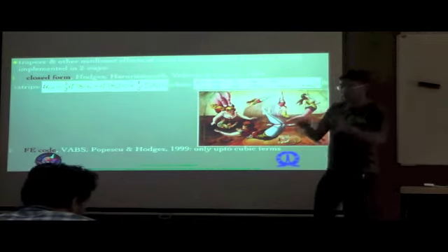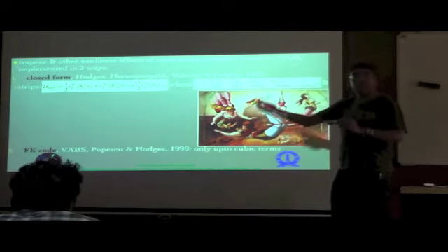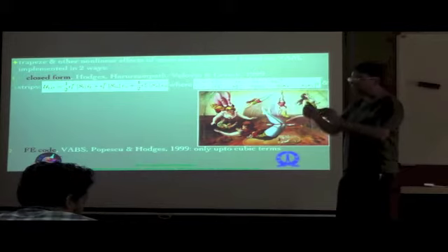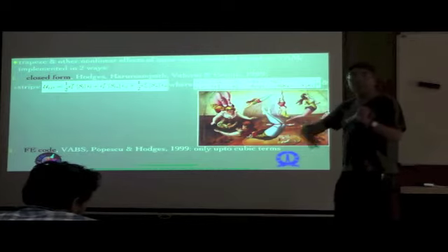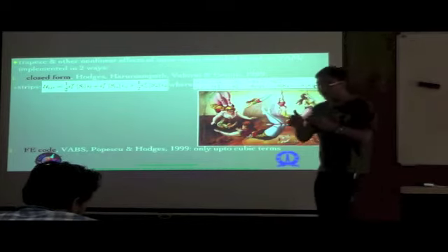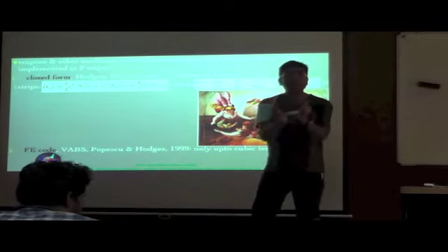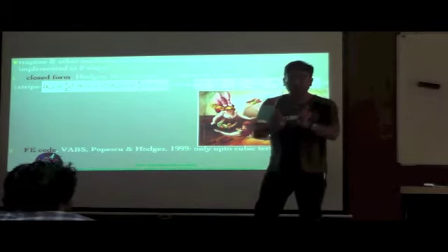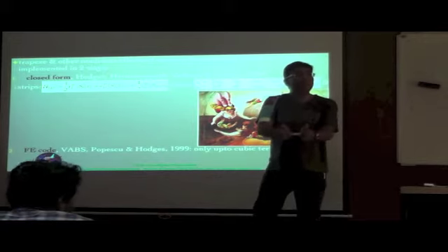The reason is, of course, that all these are results derived from the asymptotical theory, but a physical explanation for why kappa 3 squared is not there is that the energy contribution of that is of much higher order. In a thin strip like this, bending like this results in a curvature of kappa 2, whereas bending like this results in curvature kappa 3.